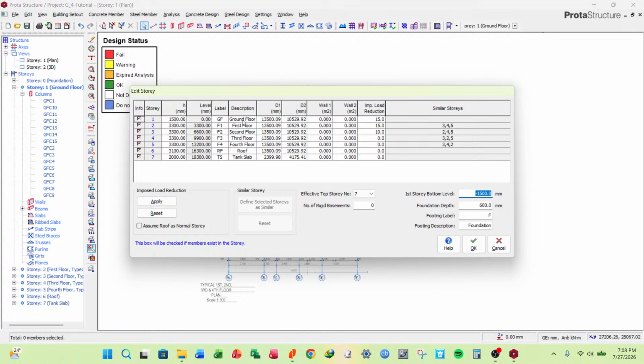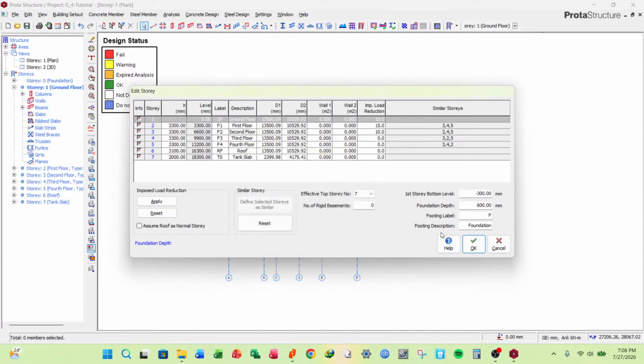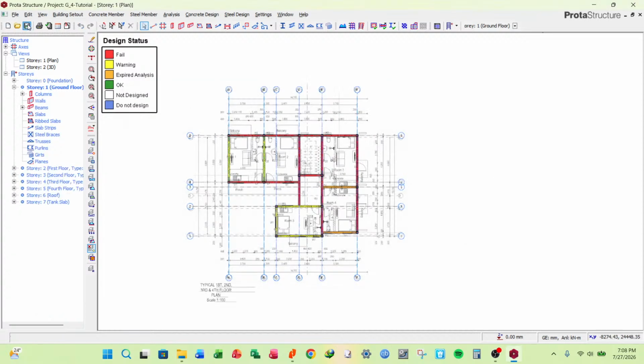It assumes that our ground floor is raised by 1.5 from the ground level, and it utilizes all this length to calculate the wind load assigned to the ground floor level. So I want us to first change this to 300 as the plinth height for our ground floor level. Then we go back and compute the wind loading. Then we shall come back and adjust later.